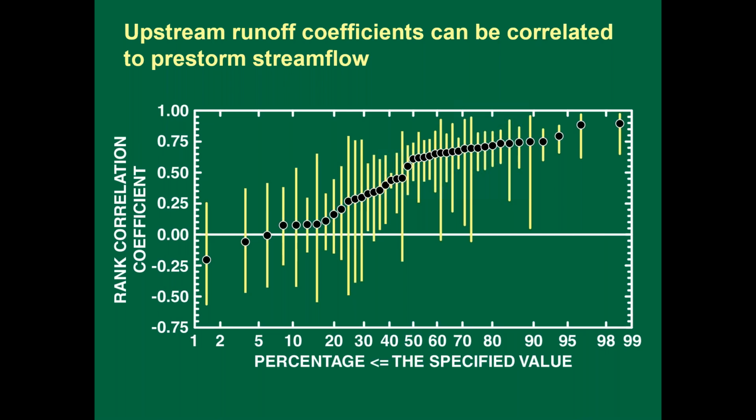So through that process, looking at different variables, SELDM has the provision for correlating the upstream runoff coefficients with the pre-storm stream flows. We found that when the pre-storm upstream stream flows were higher, that tended to indicate that the basin was wetter. So runoff coefficients would be higher in a wetter basin. SELDM has this capability because in theory, higher pre-storm flows indicate the wetter antecedent conditions that generate those higher runoff flows. Data from the runoff coefficient data set that we use seem to support this assumption.